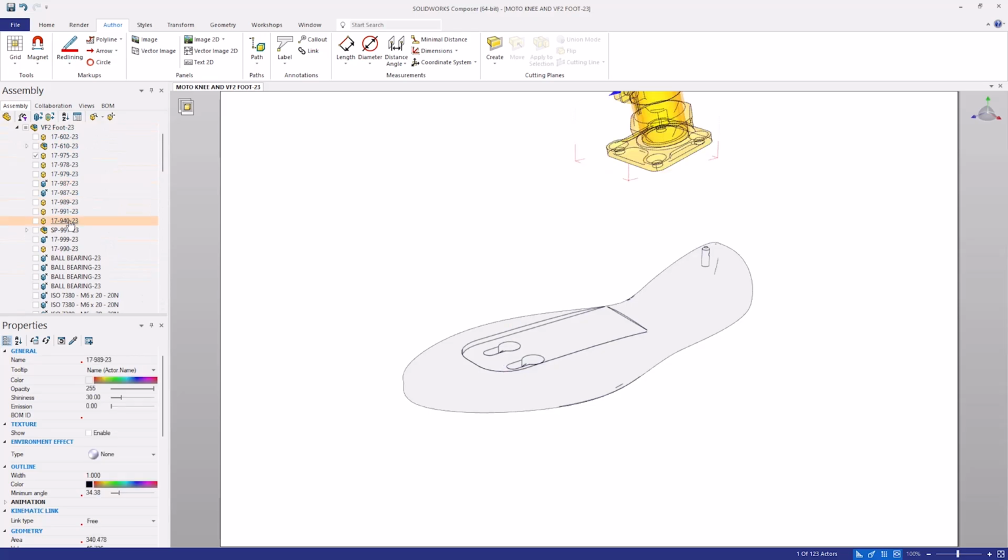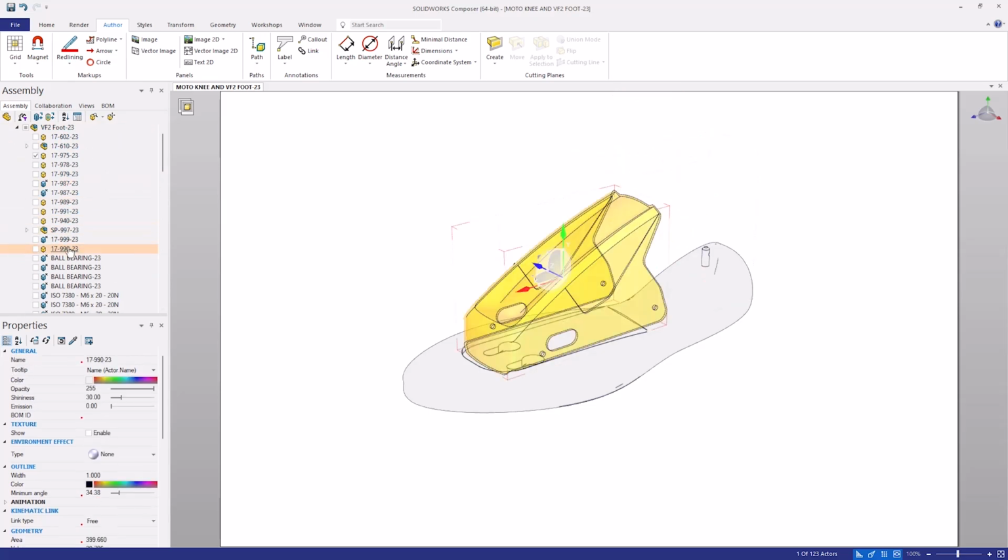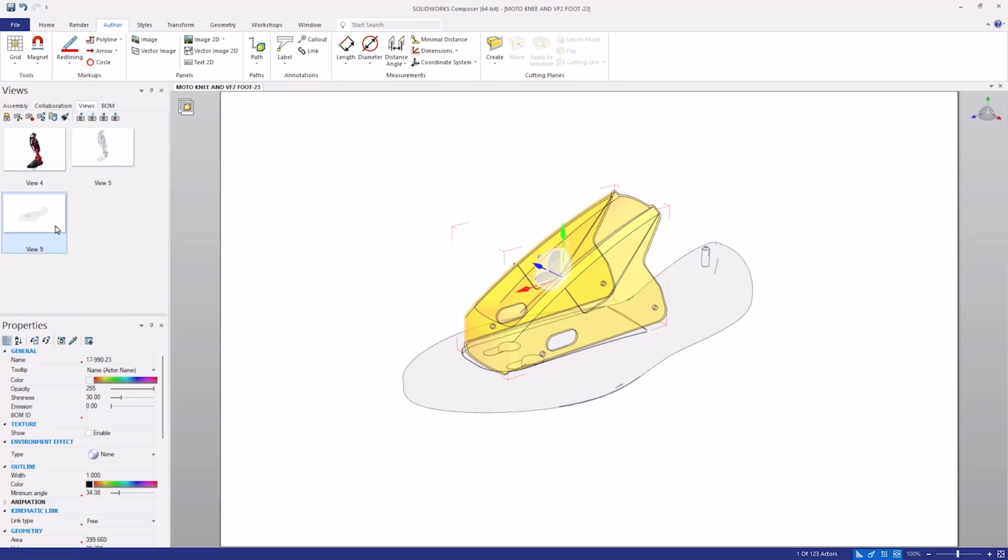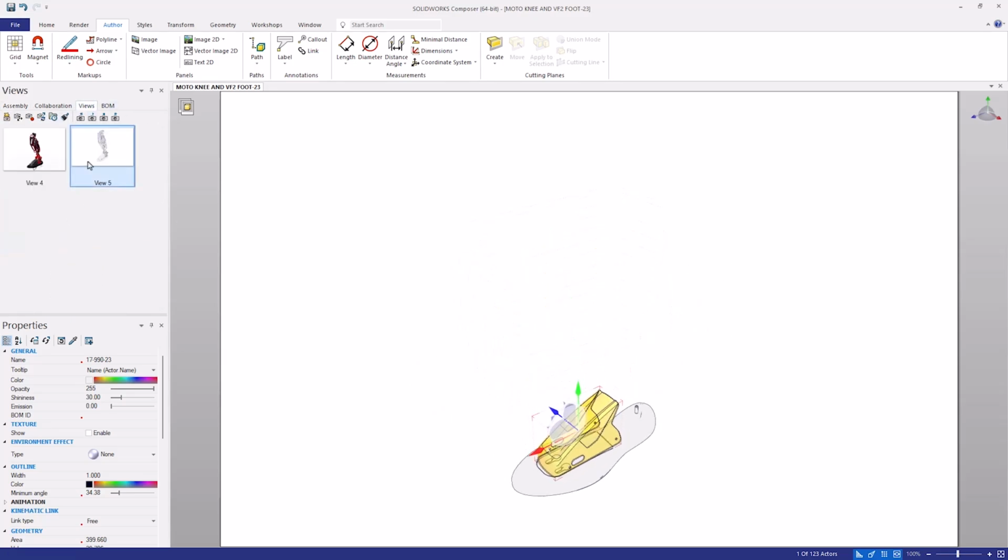Now this will work for some small assemblies, but it'll become very time consuming for anything complicated, as you will have to trawl through the assembly tree whilst trying to find out which components are going to be required, and you're going to just need to do that on file names alone. This might be possible with descriptive names, but it's not going to be much use here if you've got just part numbers. So instead we recommend the deconstruction method.